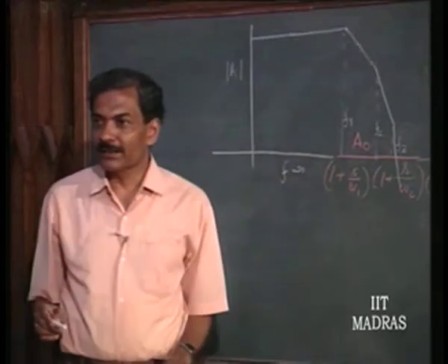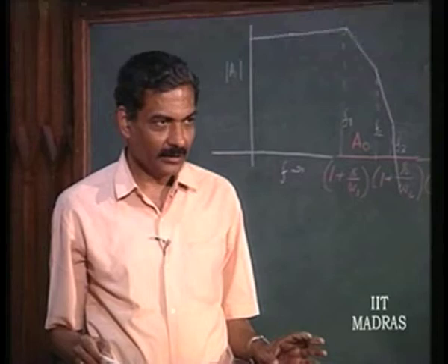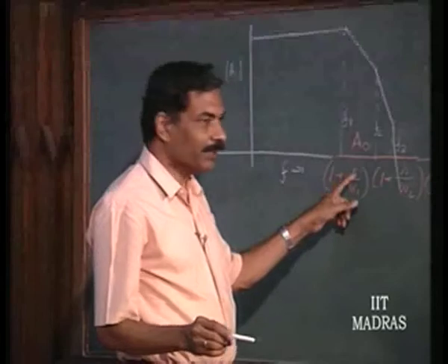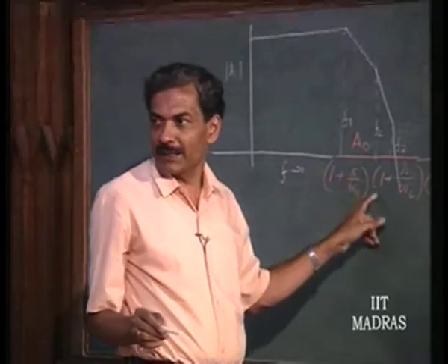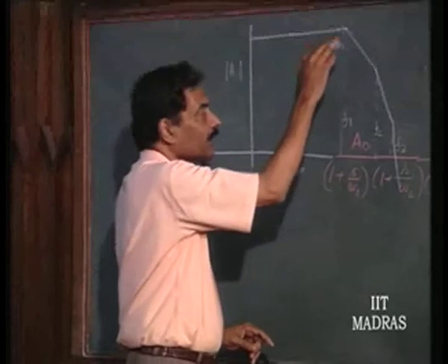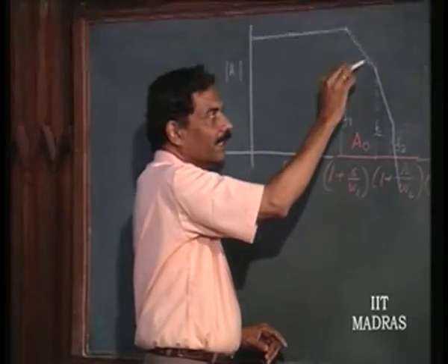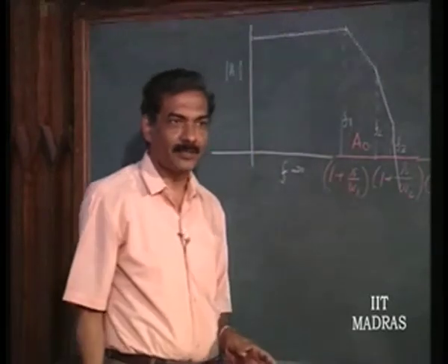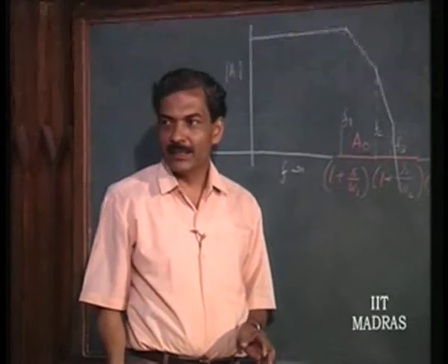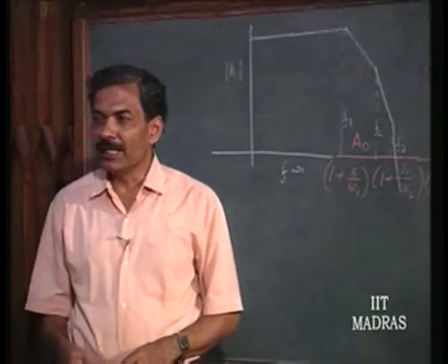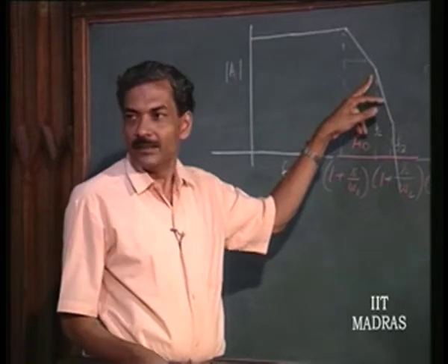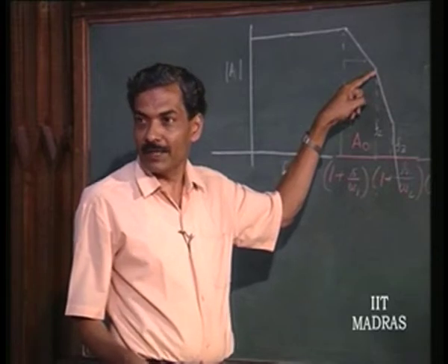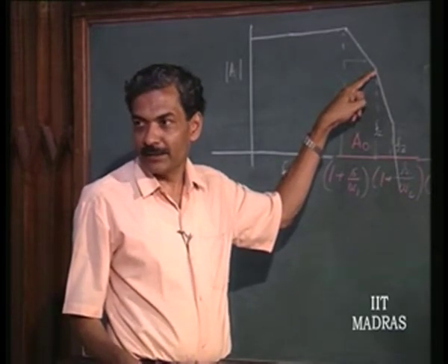At the corner frequency it is going to be 45 degrees, right. At the corner frequency, if the other poles are not influencing, it is going to be 45, because for j omega over omega 1 you will put 1 plus j. So, it is going to be 45 degrees here. By the time you go out of this, assuming that this is now contributing more of its phase shift and already has contributed enough, totally giving a phase shift of 90 degrees. So, when the next comes, let us say, this will contribute 45. So, you have 135 here, right.